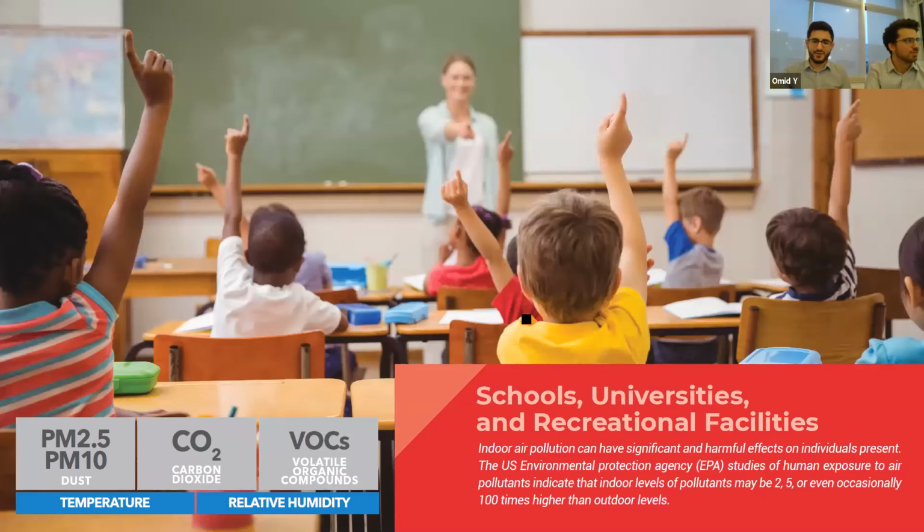Okay, so the first very interesting application is for use in schools and universities. As you may know, recently there's been a significant interest in monitoring the indoor air quality in schools. In schools, we're typically interested in the particulate matters, the CO2 levels, and also the VOCs. Basically, we want to study how the occupancy of a room affects the outcome of the learnings, or for example, transmission of disease and all of that. So this will be possible with our units.